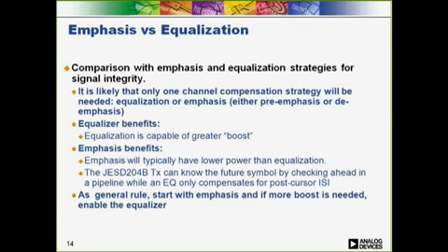I think in most cases, it will be best to use emphasis on the transmit side of the link, and then you can enable equalization if more boost is needed beyond what the transmitter emphasis can supply.